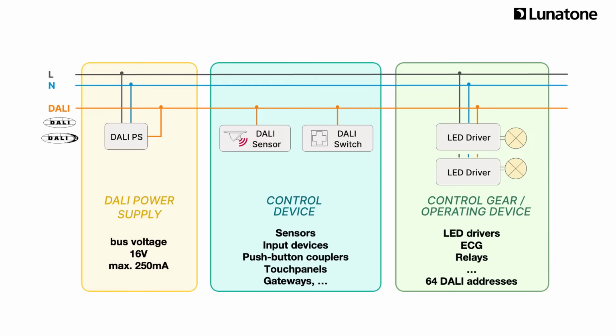Nowadays, they are of course mainly DALI LED drivers, but can also be other ballasts such as fluorescent lamps, DALI relays, and also DALI phase dimmers. Depending on the country and industry, terms such as DALI ballast, electronic control gear, ECG, or the term DALI lights is used. This setup of devices applies to the DALI standard as well as the DALI-2 standard.